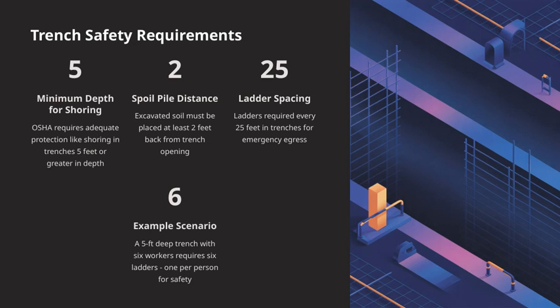Next, we have the spoil pile distance. It's important to remember that all excavated soil, or spoil, should be placed at least 2 feet away from the edge of the trench opening.